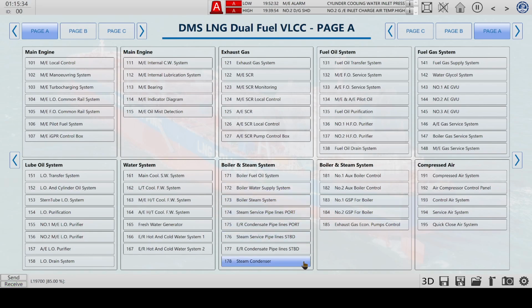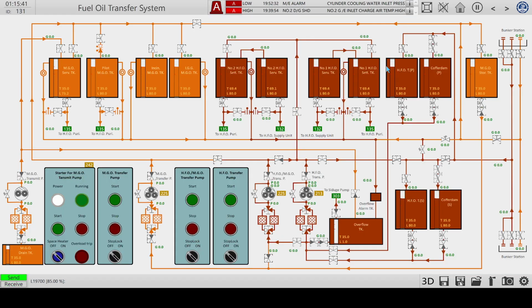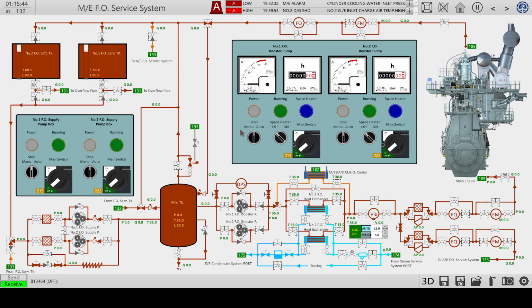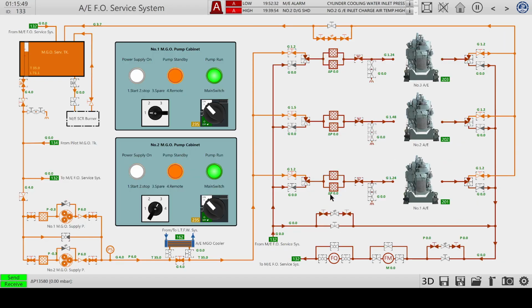With the boiler going on, we can start heating up our heavy fuel. Let's look at the fuel systems. This is for the main engine. We're going to use this circuit in a bit, because now the generators are running on this tank. And we're going to want to switch them over to the heavy fuel. Let's set this up. We're not actually going to switch over yet, but just to set up.